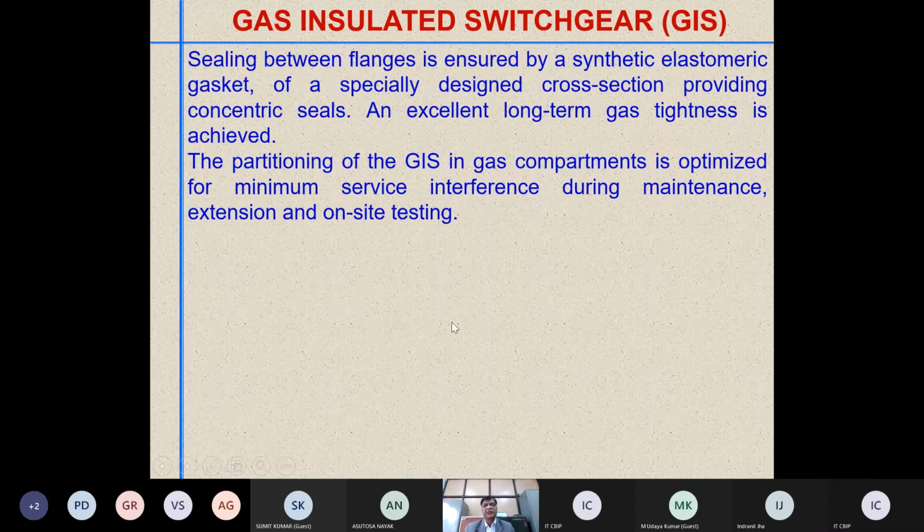As far as gasket sealings go, they have sufficient life, 15 to 25 years, but during maintenance, whether it is 5 years, 10 years, or 25 years, if you open any chamber or flange, then the gaskets are to be replaced.